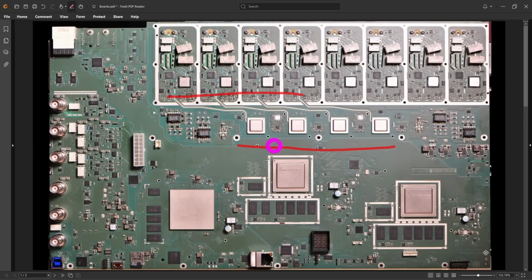There's of course a high definition mode as well, where you can play with the sample rate and take advantage of the oversampling and get more effective number of bits from these ADCs. So the entire architecture of the DSP here in the back is actually 18 bits, and that's pretty critical because it means all the additional functions are running on that 18-bit architecture, so nothing slows down when you go into high definition mode. That's not an easy thing to do on its own. Each of these chips has to support 400 gigabit per second in order to accommodate the 4.5 million acquisitions per second and the 18 million waveform update rates. It's just a crazy fast oscilloscope.